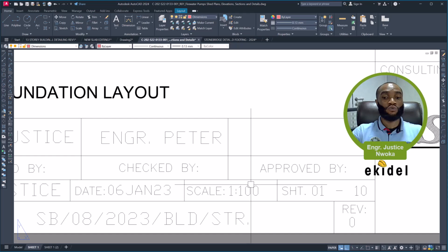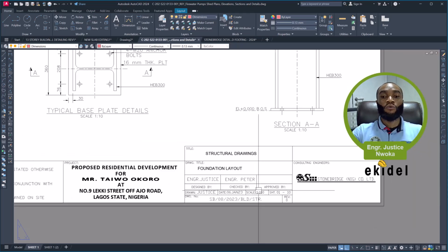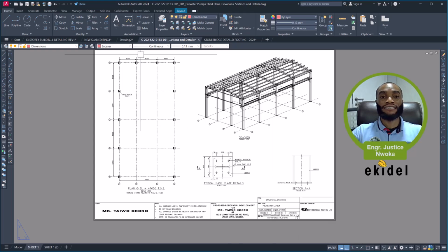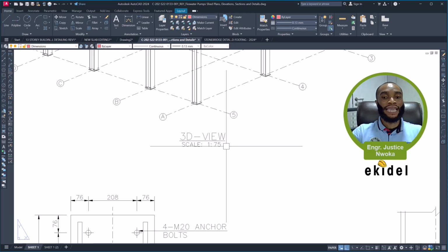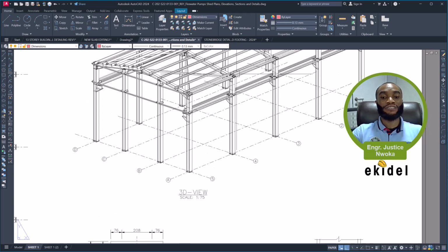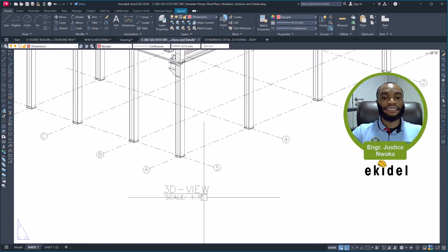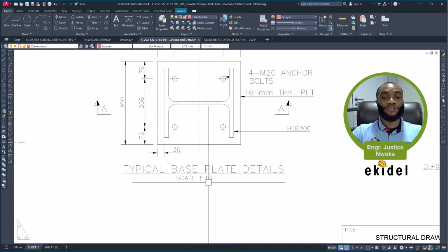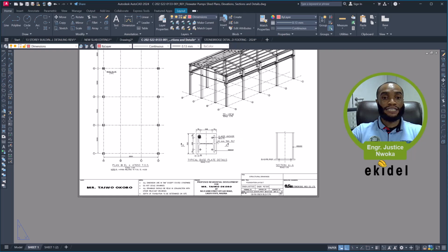What the highest one means is that this drawing was done by scale 1:100, but if you see a scale under any of the drawings, know that it is the scale they used to bring that drawing to the viewport, and also the scale they used for the text height. For example, we use scale 1:10 for this text height. We are not done with this. Let's now move on to the other page.